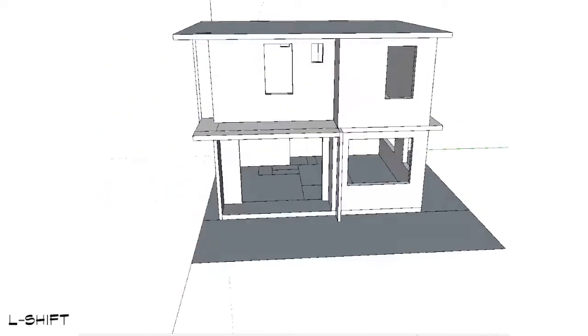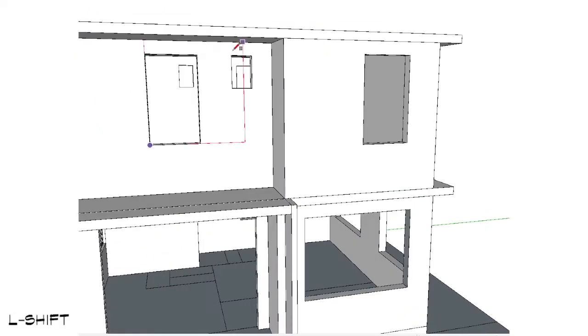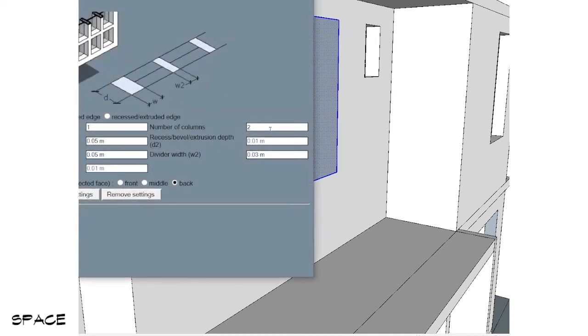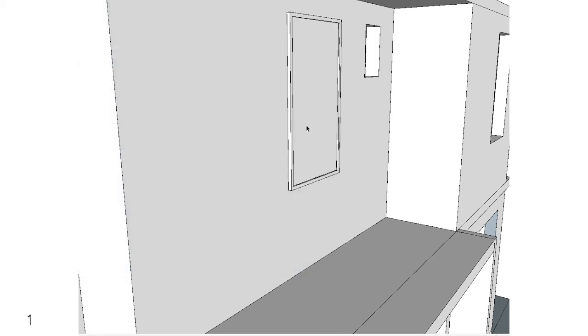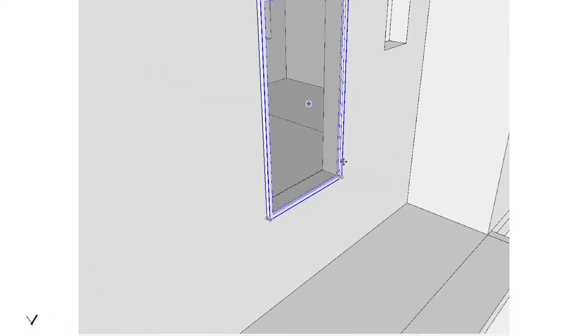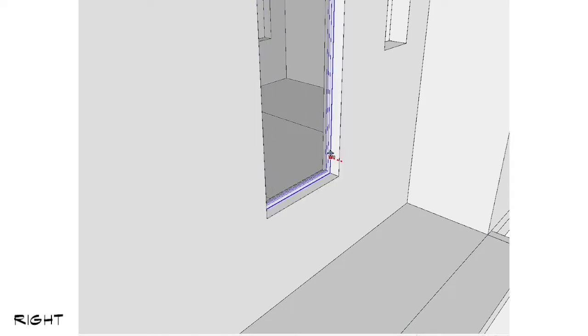Alright. In this case, I'll have this as maybe a half type awning, or let's say this is a casement window. So you can use the same panel thing or the other tool. Shift G and W2. Okay. Move back a bit, use the arrow to align.